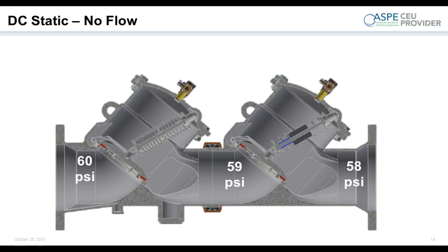So they have a differential meter, they hook it up, you bleed through some water, and then you're looking for it to settle on or above 1 psi for each of those checks. Then there'll also be things like shut-off tightness tests to make sure no water is flowing that could interfere, but the heart of what they're testing for is the differential across those first two.